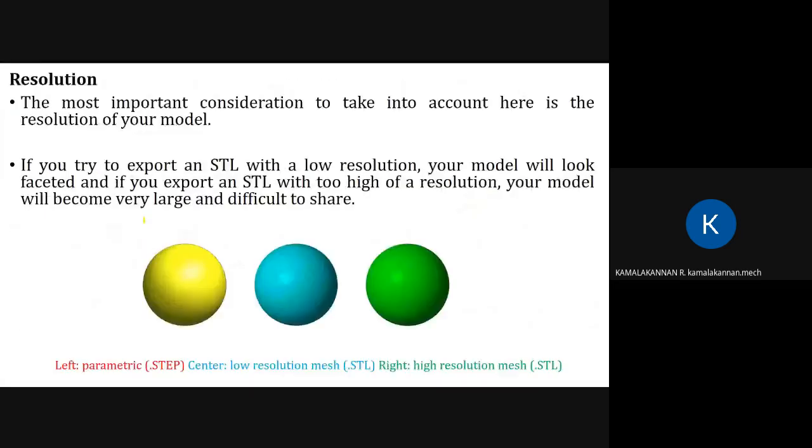So resolution is also an important thing, which will decide how much data will be carried over. When you give too high a resolution, more data will be carried. When there is a low resolution, you will find that your product is faceted, meaning many faces will come within the product. When it is a proper resolution, you will get the right model with a low data file.